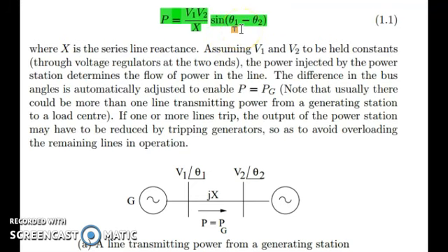So series compensation brings about so much control into the system when compared to shunt compensation, according to me. But the risk is we are adding a series component in the transmission line, and if that component fails, the entire system is going to fail. So there are pros, there are cons. Let's see the basic principle of compensation while using a series compensator, and then we can see the different kinds of series compensators and learn the pros and cons of each of them one by one.